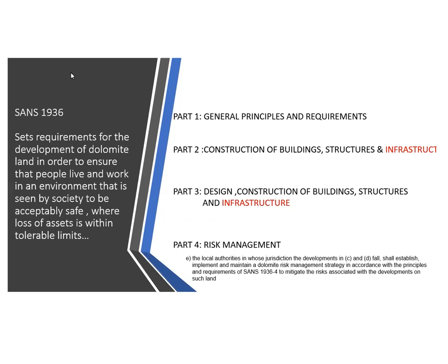As I mentioned, there is a standard that sets the requirements for development of such dolomite land. These specific requirements need to be done by a geologist. There's a lot of high-level professionals that get involved. The point I'm trying to make is that it's covered in four parts. The first part is where they get that classification. A competent person will conduct the geotechnical site investigations, establish data, and then get to those categorizations, D1, D2, D3 and D4.